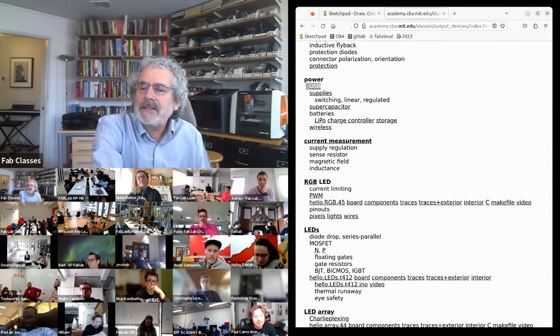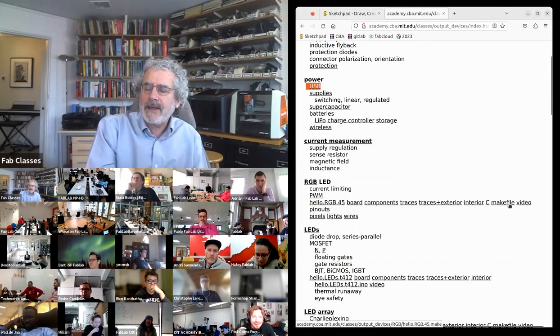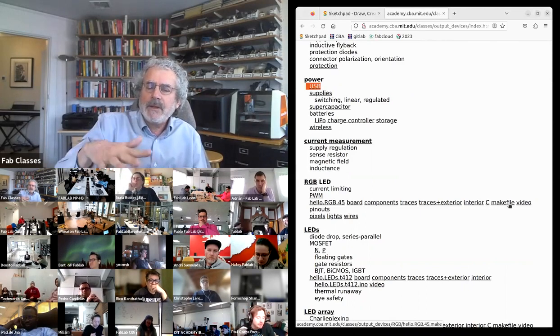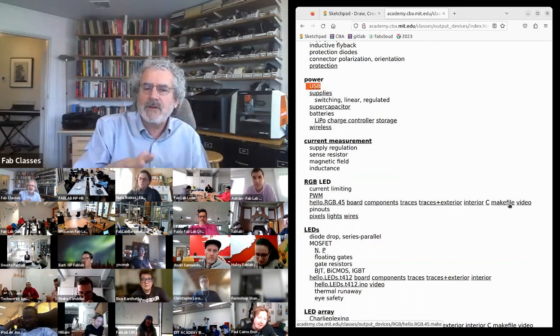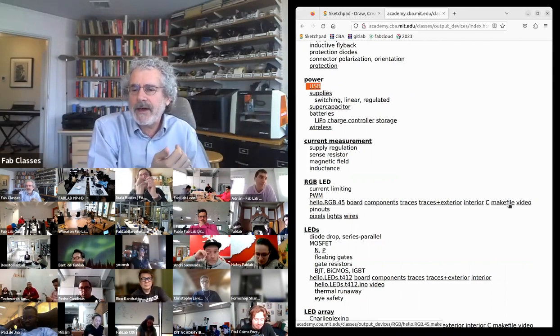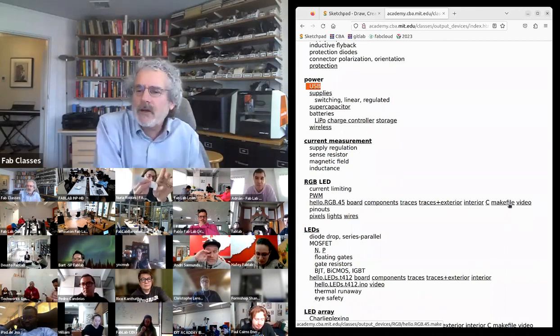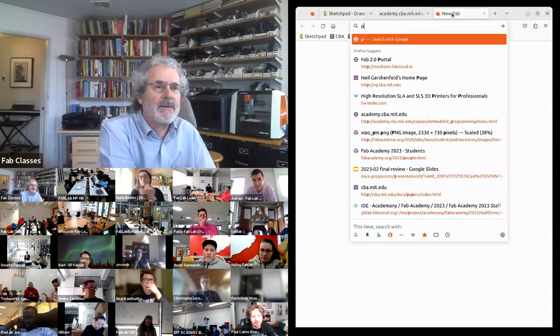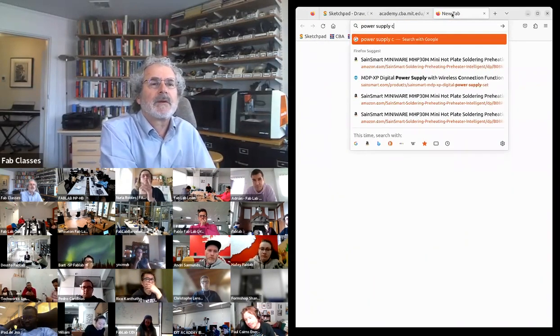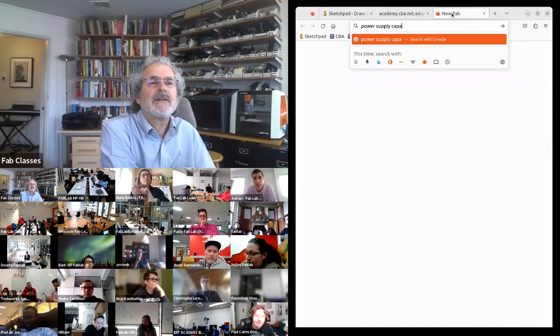Let's see, Michael's asking about dangerous. So the issue with supercapacitors mainly is just they're limited depending on which one you get to, like 1.8 or 3.3 volts. If you go over that, you kill the supercapacitor. I'm not aware of other dangers on supercapacitors. Oh, but yeah, what I was referring to is power supply, not a supercapacitor.